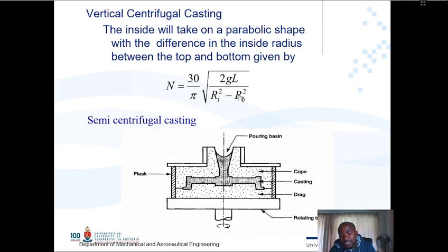other, practically and analytically. When you're looking at this, we can see that if we have these two together, this value here becomes 0, and this factor of the equation becomes infinite. Practically, if you have vertical molten fluid poured into a hollow tube which is rotated vertically, you will always have that fluid trying to go down because of gravity, and because fluid deforms, you will always have a lot more at the bottom than at the top.